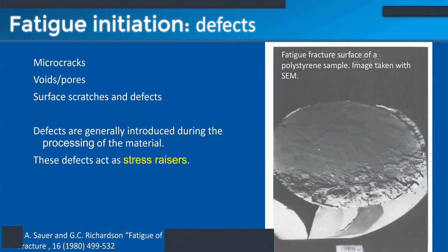So if you're designing a device, you want to be aware that this phenomenon of fatigue can potentially happen. You probably want to do some calculations or some simulations to figure out what the local stresses would be around those areas, so that you can keep the applied stress to the device lower than the yield stress, even in those areas, and try to prevent fatigue from occurring. Try to prevent failure from occurring, I should say.